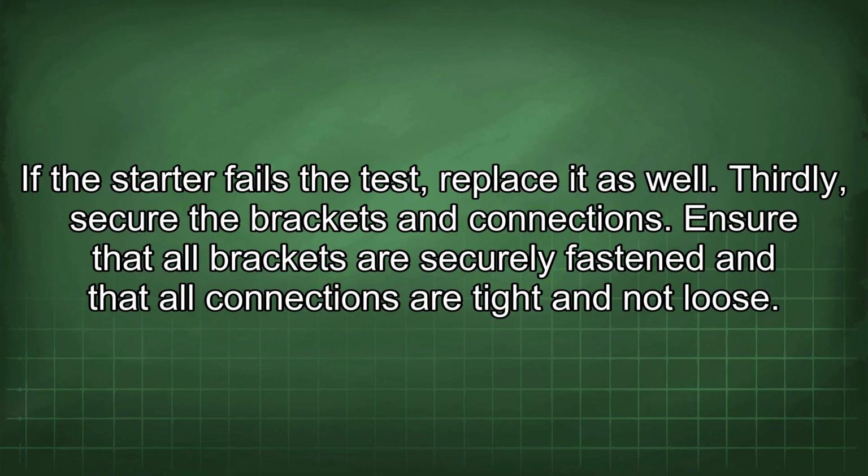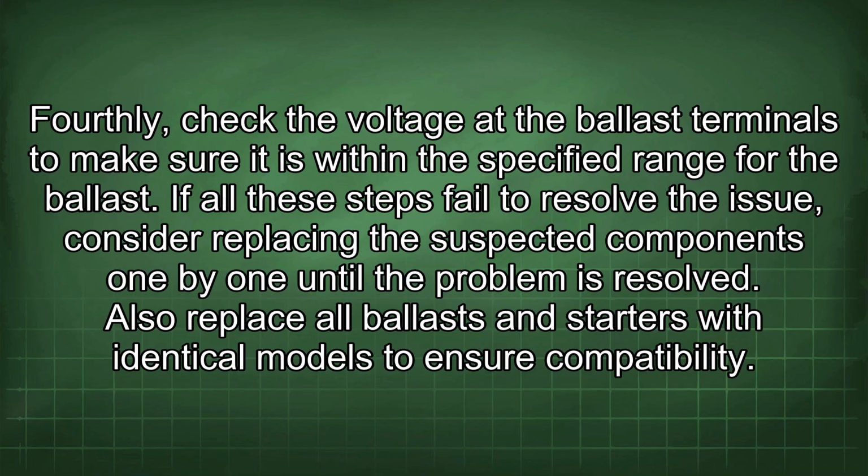Thirdly, secure the brackets and connections. Ensure that all brackets are securely fastened and that all connections are tight and not loose. Fourthly, check the voltage at the ballast terminals to make sure it is within the specified range for the ballast.